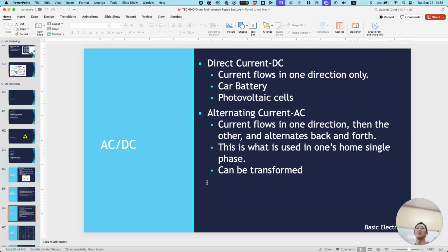So anyone done commercial electricity work? Even if you change out the outlet on your wall, if you pull it out, you'll see 3 types of wires. It's going to be a black, a white, and then either green or just a copper wire. Just look at this thing. That's exactly what it's wired to each of these. I believe this is your black, which is your hot, and then this is your neutral, and then this is ground. So you don't technically need ground. That's why you see some devices just have a 2-prong plug. But for safety reasons, it's better to have a ground.